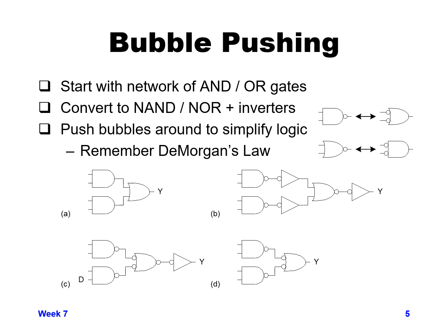So the inverters following the NAND gates, we take those inverters out and show them as bubbles attached to the input of the NOR gate. So now we have a not NOR gate. That gets rid of, quote-unquote, two inverters from our logical function. And then finally, in the lower right section, we take the inverter at the output of the not NOR gate and combine the bubble of that inverter with the bubble at the output of the NOR, and now we have a not OR gate.